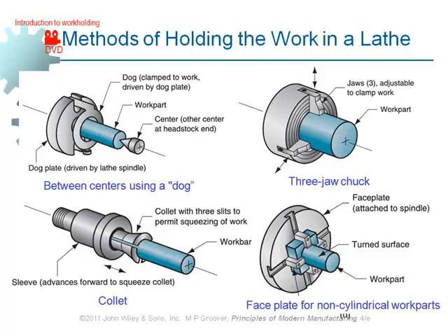This is, of course, the most common method of clamping the part onto the chuck, right? This is what we have seen in the workshop, right? And as you can see, if the shape of the workpiece is non-rotational or it is unusual, then you can make use of the 4-jaw chuck like that or a face plate in order to clamp the part.